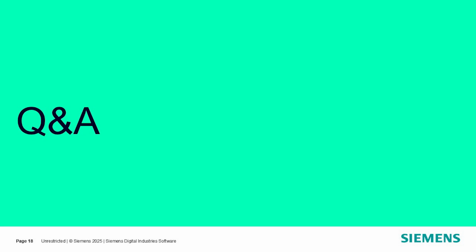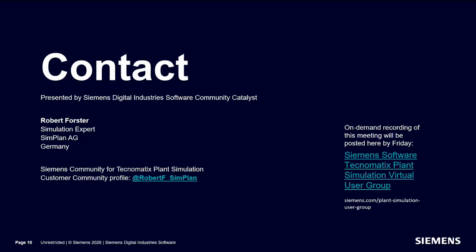Is there some documentation available for the libraries? So there is an integrated help file within Plant Simulation. It's the old technology, so to speak, with CHM files. If you click on the objects there, there should be, for every object, help on object at the top, and then contents or help, also an object, and then a CHM file should open up to give more explanation on how processes are working, how parameters are used, an example, step-by-steps, for example, for a single station.